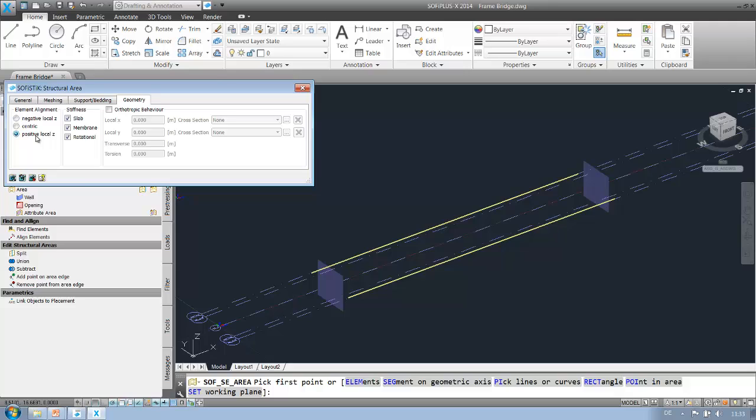And I also have to implement an orthotropic behavior, because the shell element won't bear any loads in longitudinal direction, it should only transfer the loads in transverse direction. That's why the shell element will have an orthotropic behavior without a membrane and bending stiffness in longitudinal direction, so that we can avoid double stiffness.